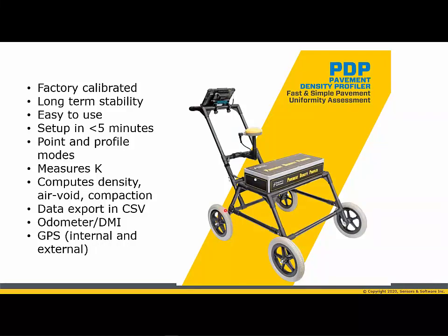The positioning is controlled by an odometer, which is on one of the wheels. You also have the option for having GPS. The unit itself has an internal GPS for positioning. And the data shows up here on a tablet, which is linked by a wireless path to this device. So the unit itself runs independently of the tablet. The tablet essentially is a display device, starts and stops, but other than that, everything else happens in this box. So you can have one box or several boxes running, and you can look at a multiplicity of data sets. The data is all self-contained in here, which you can export on demand to a CSV file, which allows post-data acquisition analysis. So that's the PDP in a nutshell.